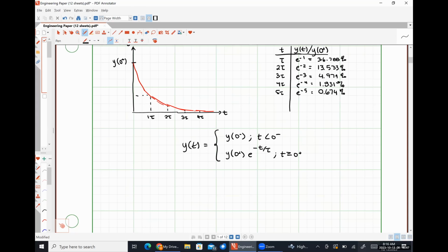And our fourth step would change to just say, find the time constant of the circuit during the transient condition, as opposed to find LEQ and REQ or find CEQ and REQ, because that all means literally the exact same thing, okay? So this is the generic equation that I'm going to be working with from here on out because it is the most general case and is applicable for all first order circuits.